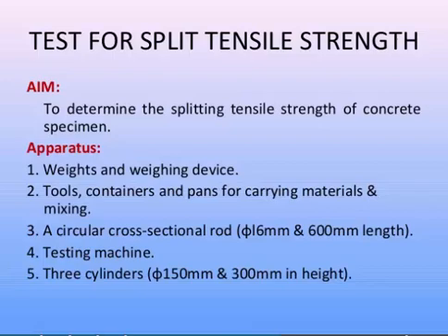Then a plate or supplementary bearing bar is essential. It is employed when the diameter or the largest dimension of the upper bearing face or lower bearing block is less than the length of the cylinder to be tested, and the plate width is kept as 50 mm.